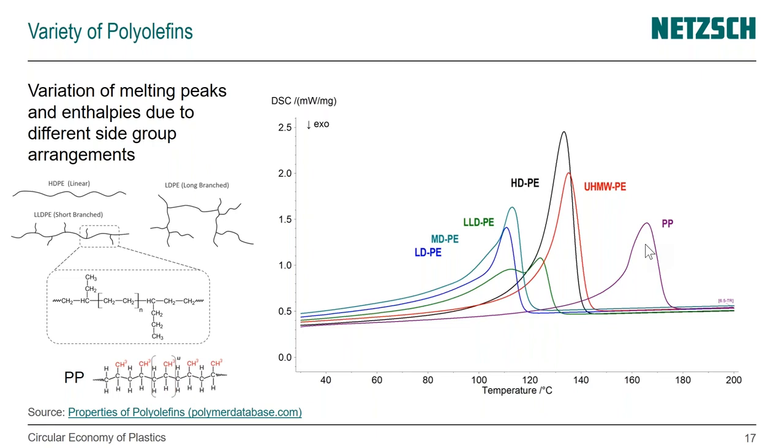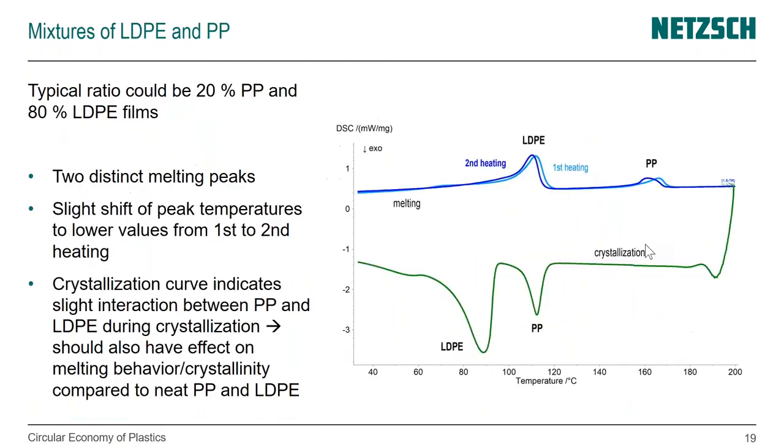So if we have small molecular weight portions in our material, crystallization will happen faster. And that's also what I meant when I talked about this effect of crystallization here. Because PP is in the mixture and it crystallizes first, it creates boundaries on which LDPE starts crystallizing on. So the PP acts as a nucleation agent.